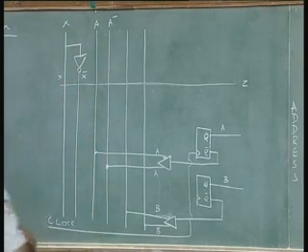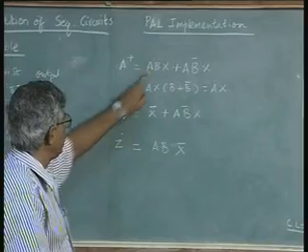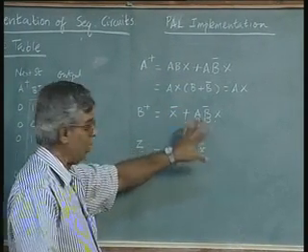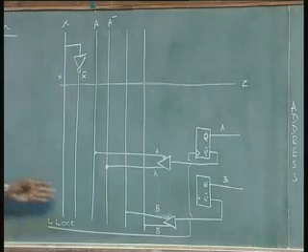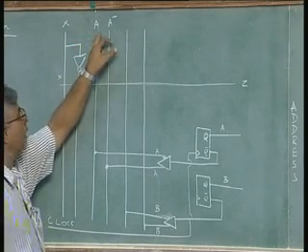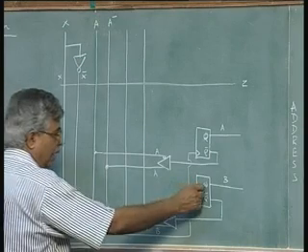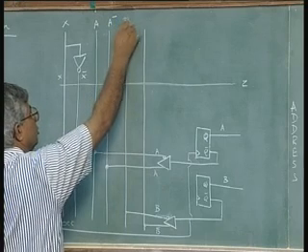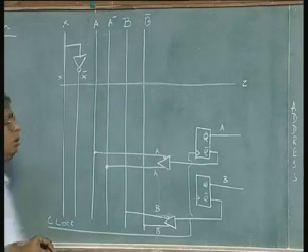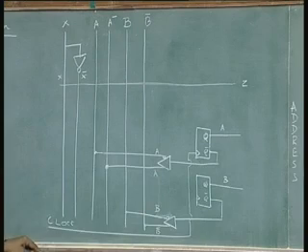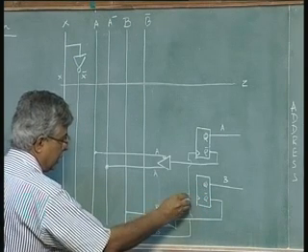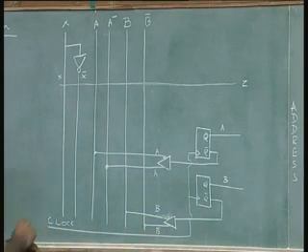See, in the combinational logic here, I need X, A, B. So I need X bar, A bar, B bar. Since all of them are required, I need to create all of them here. X, X bar, A, A bar. Similarly, the second flip flop will have the output B derived here. Second flip flop B, this will be B bar fed here, and this is a clock, though this flip flop is common clock.